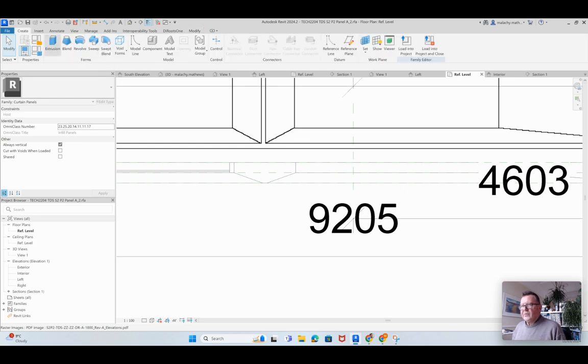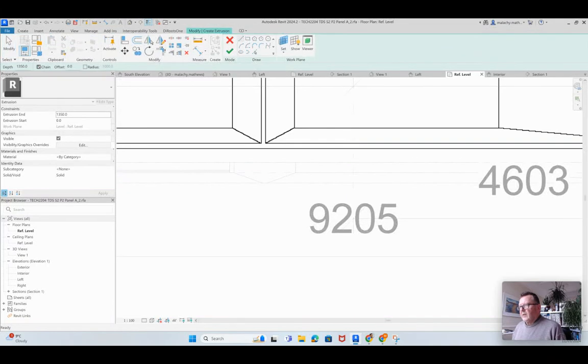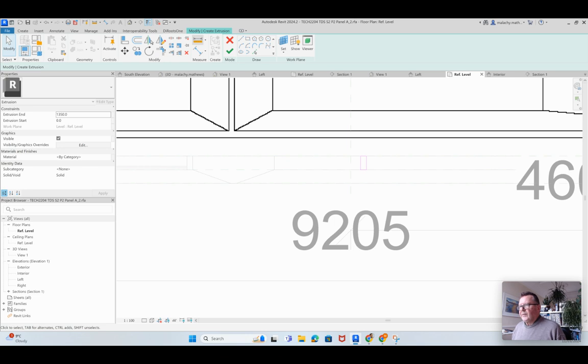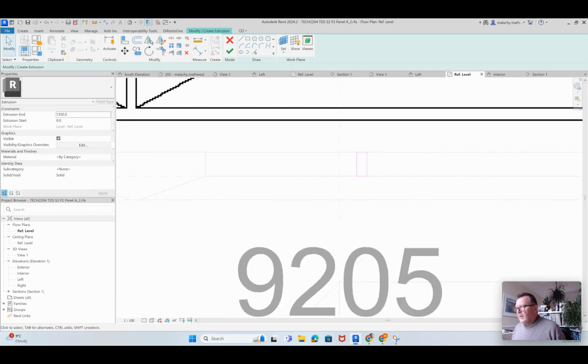So we'll do an extrusion and take line work here and so it was somewhere in around here. And I'll just make that 60 as well. That's kind of what I'm making my frames for the moment. Now let's just check that distance there. It's 8. Needs to move maybe 10 mil or so.